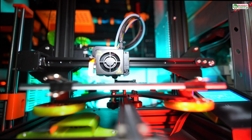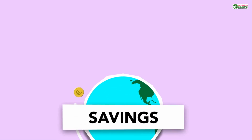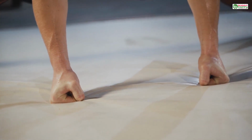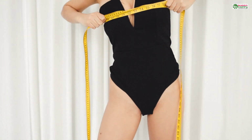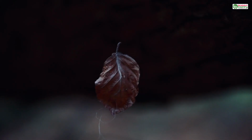But, and this is a huge but, it has weaknesses. PLA is brittle. Drop a thin PLA print, and it's likely to snap. It also has a very low melting point. Leave a PLA object in a hot car on a summer day, and you might come back to a warped, melted puddle. So for looks, a plus. For strength and durability, not so much.